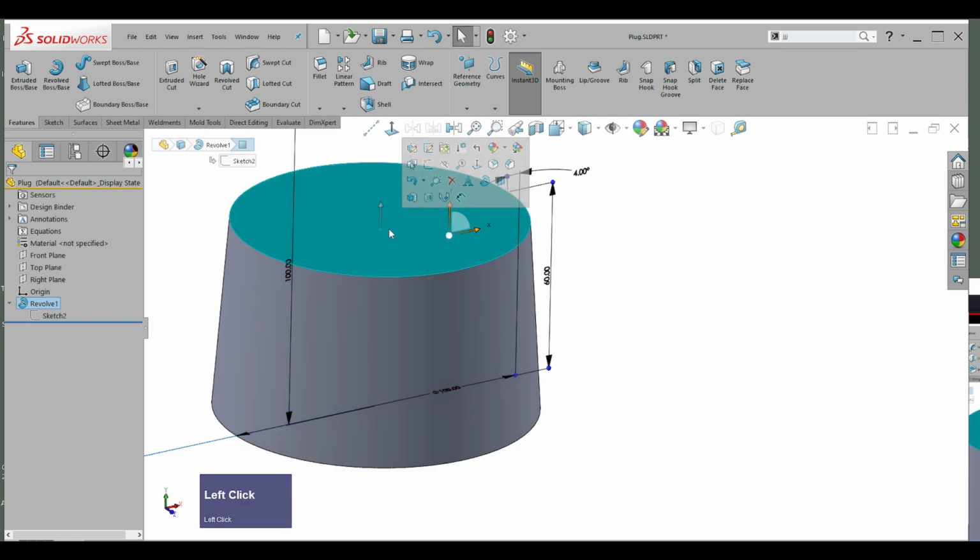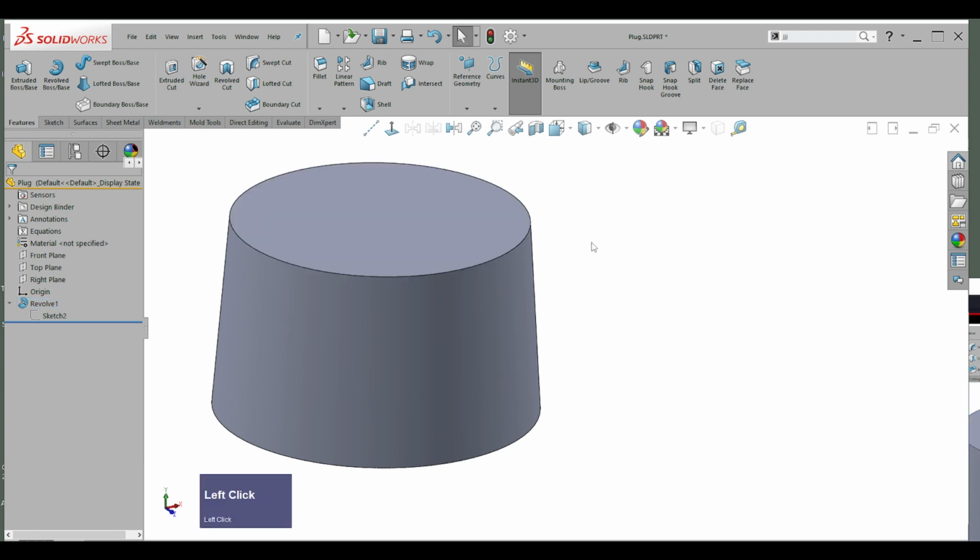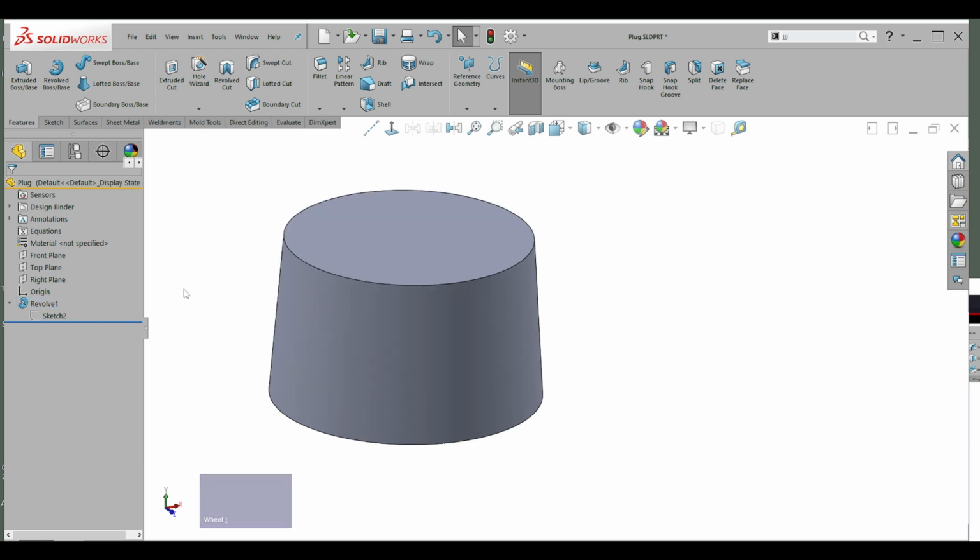You can also do things like pull faces. If I pull this now, unfortunately, it's going to break the link between the sketch and the origin point, and then that's a mission to reestablish. So I'm not going to do that, but I'll show you at a later stage what we can do with that in other situations.